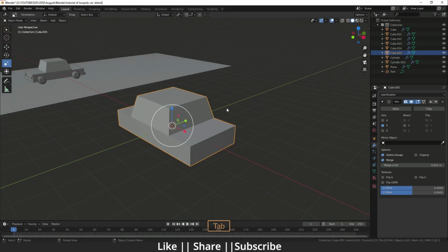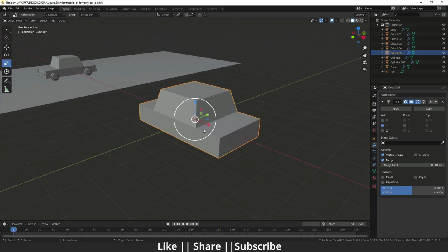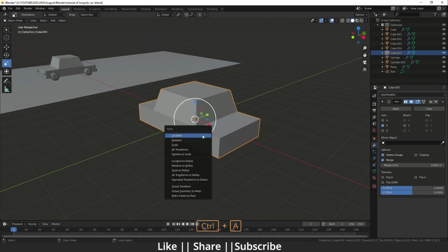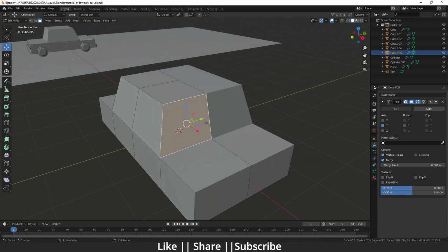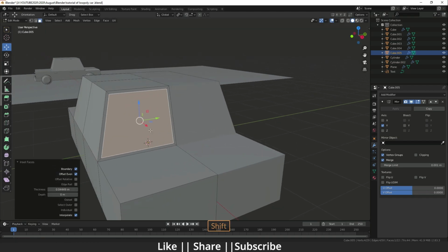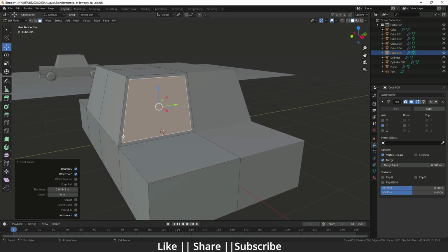For that you have to exit from edit mode and press Control A, and here you can see Apply Scale. So when you apply the scale, and after that you do the insert, here you can see it's inserting equally. Now it's inserting equally from each and every side.